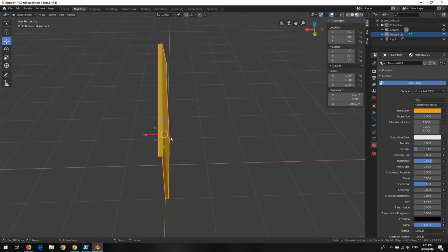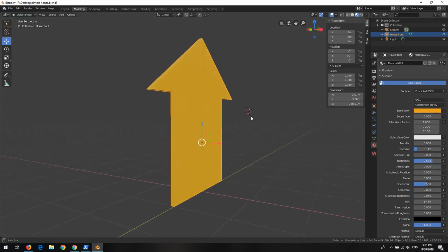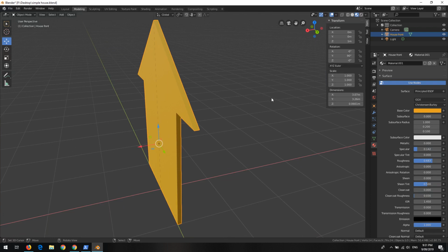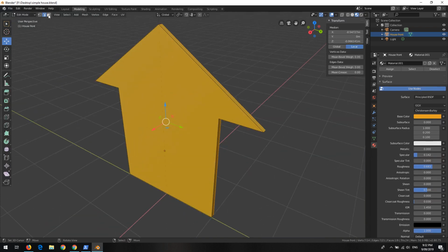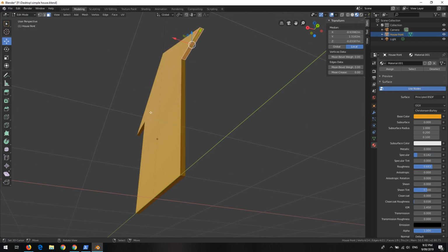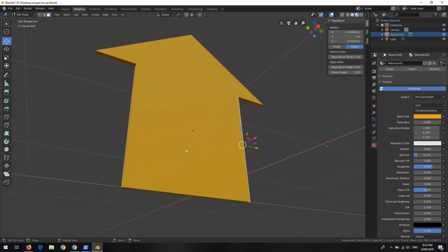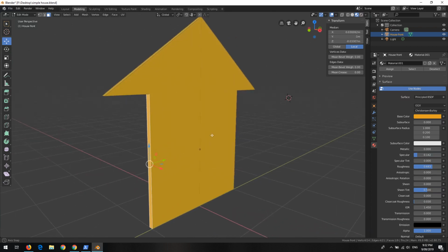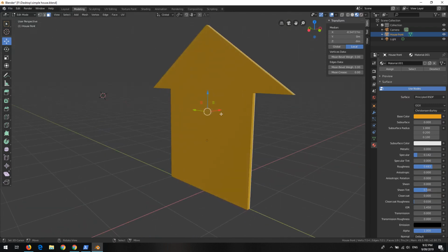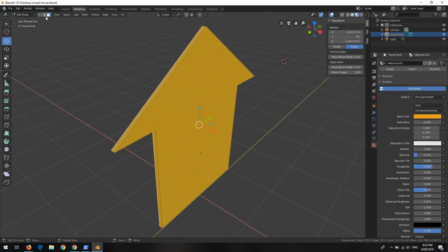Now we have a solid object, like in the real world, and now you should be able to see, if we go to edit mode by going here or by pressing Tab, we go to the face selection mode. You see one face, we have another face, we have several faces. You can right click and select individual faces and do some editing. You can see editable faces, although all these are triangular internally. Let's go to edge selection mode.